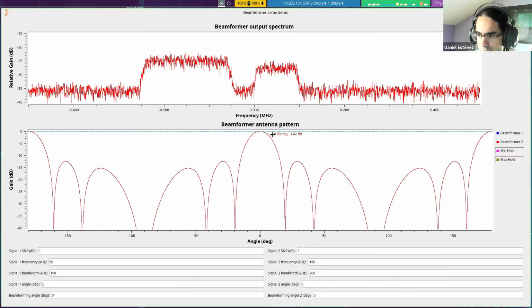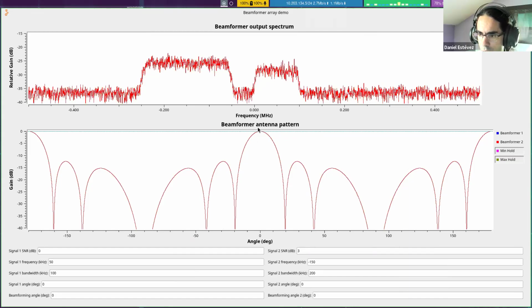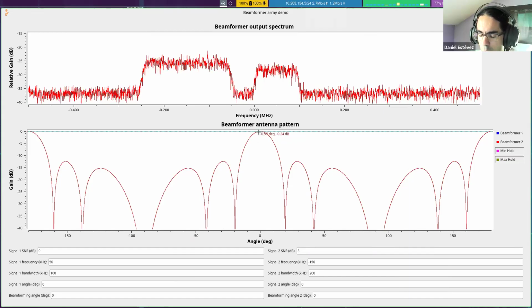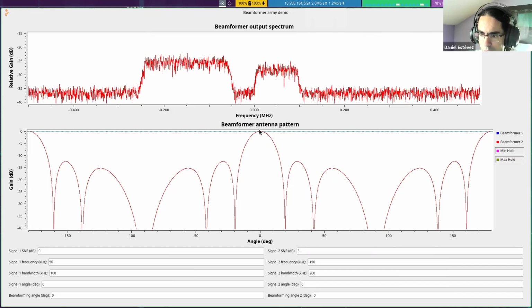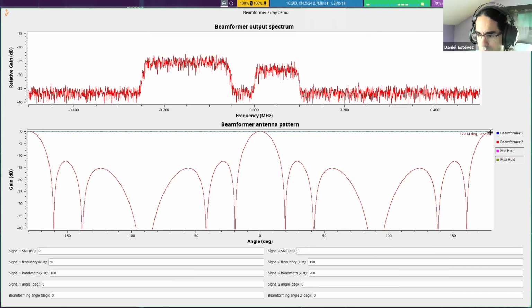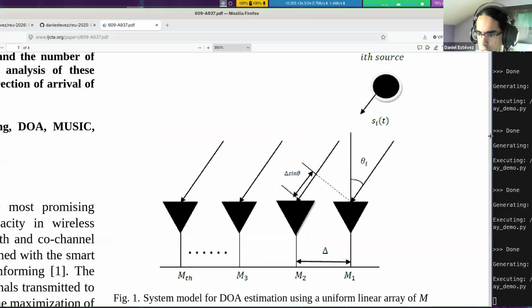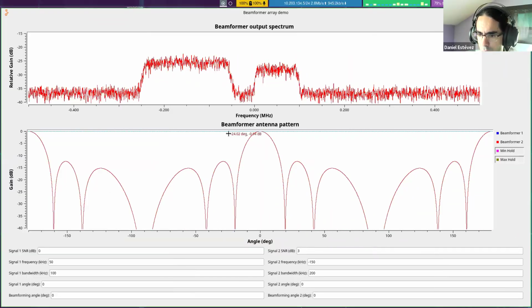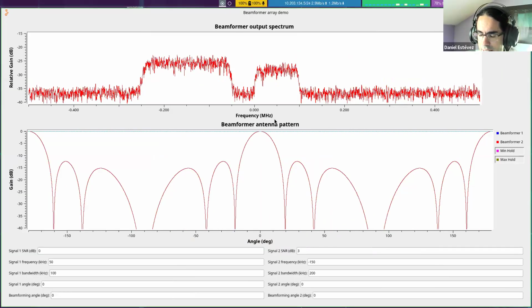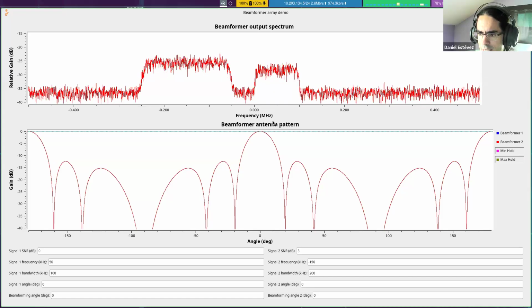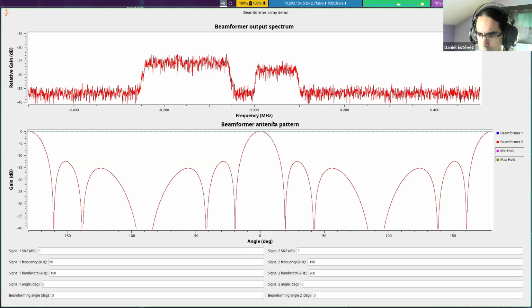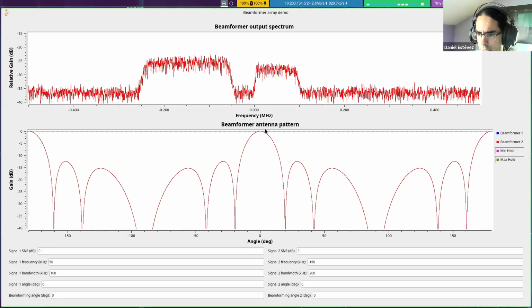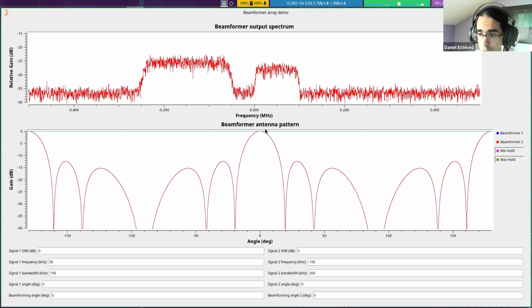Yeah, so basically in here I get essentially no grating lobes. I don't have a way of distinguishing between signals coming in from the front or from the back, which is minus 180 degrees. And that's built into the design because if the signal is coming from the up direction, which is the front, or from the down direction, the array looks the same. But this is the way of having no grating lobes: basically, putting the antennas half a wavelength apart or less. No one does that in radio astronomy. It's not practical. They can do that in your Wi-Fi router, for example.